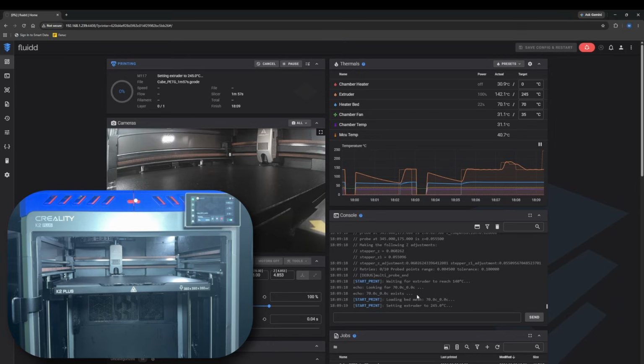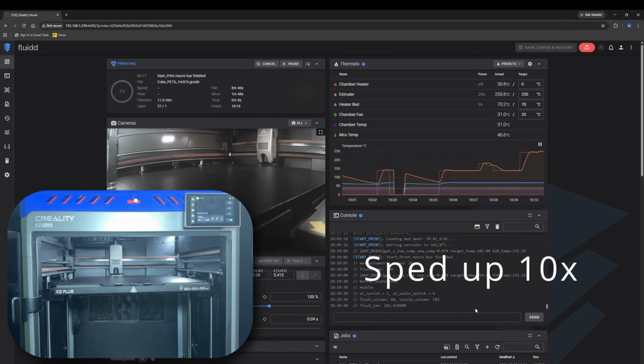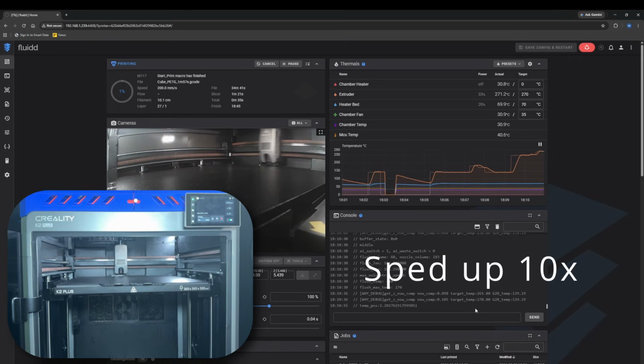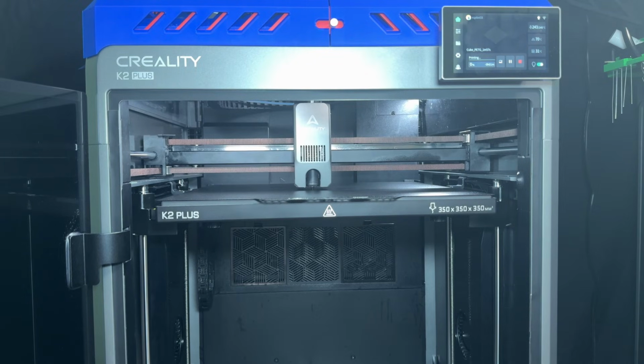It already had a bed mesh with the 70°C heater bed temperature and the 140°C extruder temperature, so it skipped making a bed mesh and it's going back to purge material. And you can see that right down over here in the small console. Now instead of going to the front left to do the normal purge line, it's doing a short, wider purge line near the part.